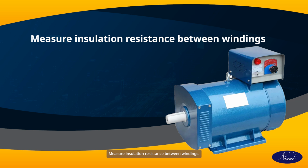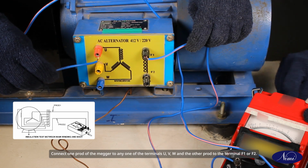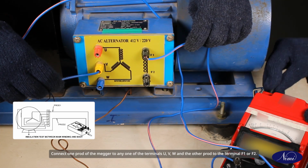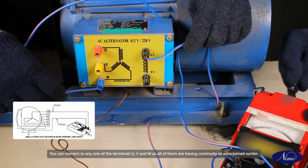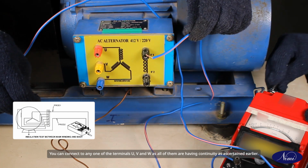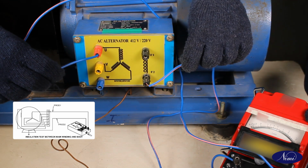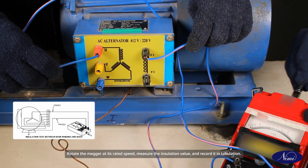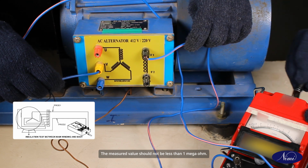Measure insulation resistance between windings. Connect one prod of the megger to any one of the terminals U, V and W and the other prod to the terminal F1 or F2. You can connect to any one of the terminals U, V, W as all of them have continuity, as ascertained earlier. Rotate the megger at its rated speed, measure the insulation value and record it in tabulation. The measured value should not be less than 1 mega ohm.